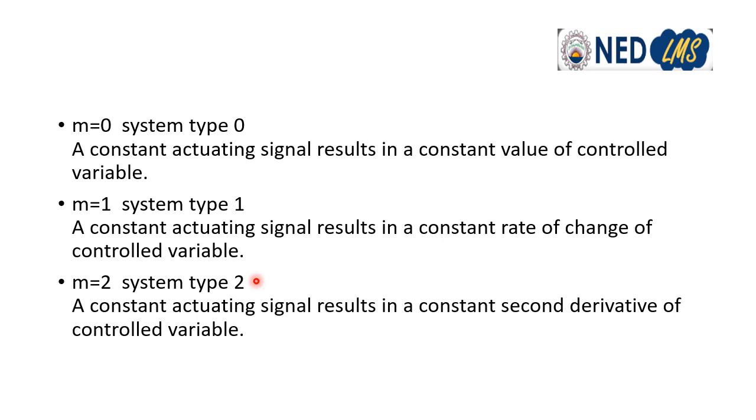Remember that at that point we added an integrator, 1 upon s, when we considered the displacement or position as the output, and we did not include that integrator when we had velocity at the output. So we include one integrator, that is 1 upon s, in the block diagram.